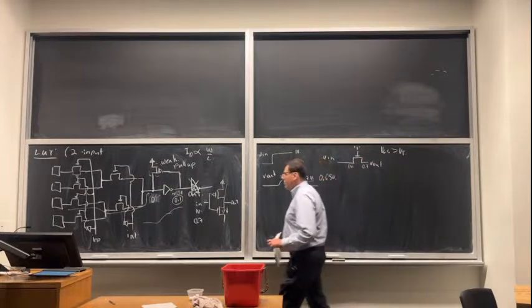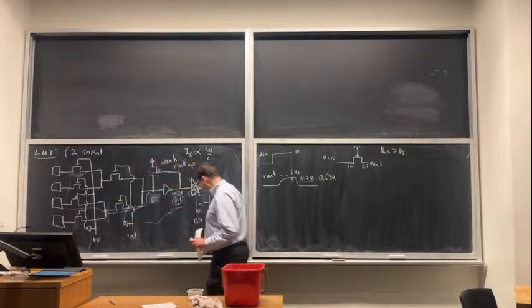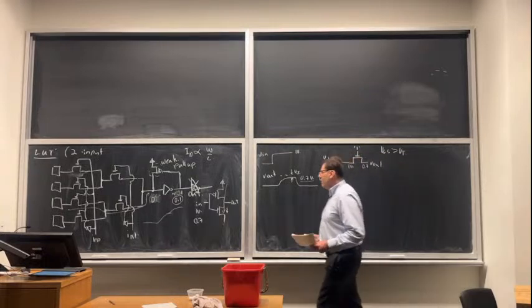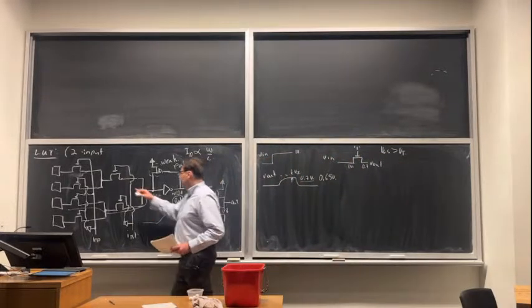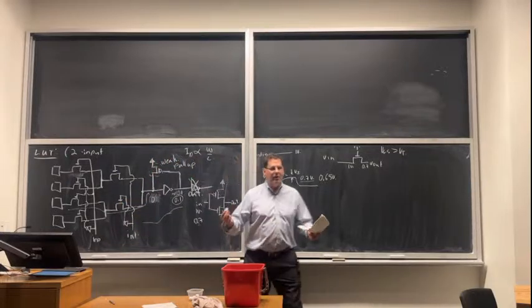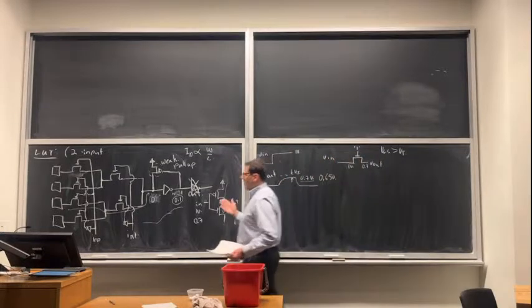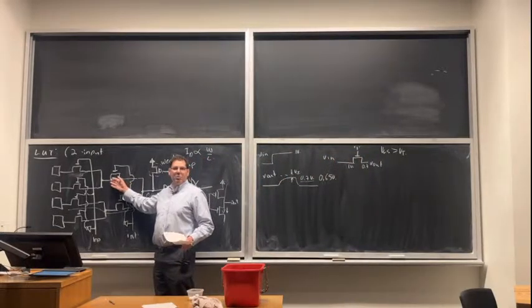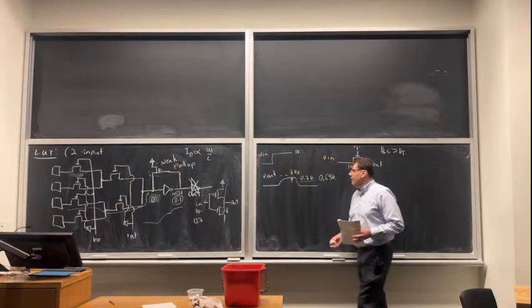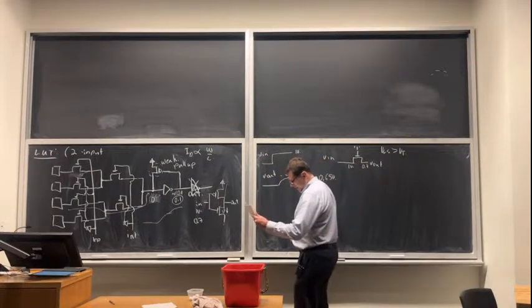For some of the most advanced process nodes, where VT is a larger fraction of VDD, just so you don't have too much leakage, you may have to switch to transmission gates. The second paper that you were assigned last week talks about that. It analyzes where that trade-off is. It doesn't fundamentally change how you build this though. You basically wind up doubling the number of transistors in this tree, but otherwise it looks pretty much the same. Does that make sense?